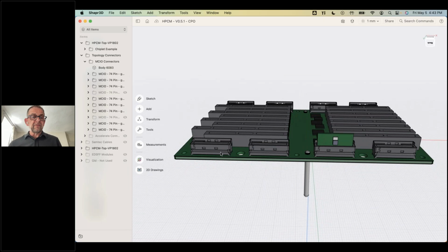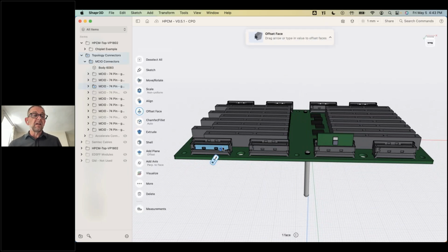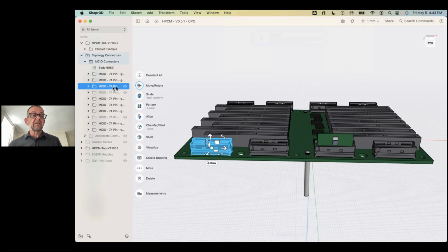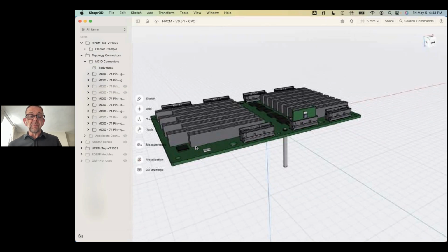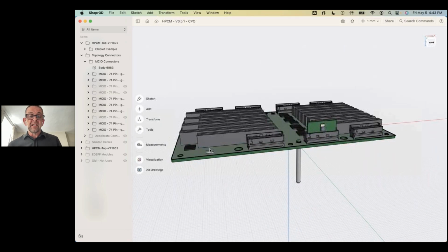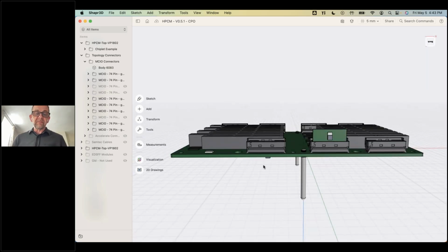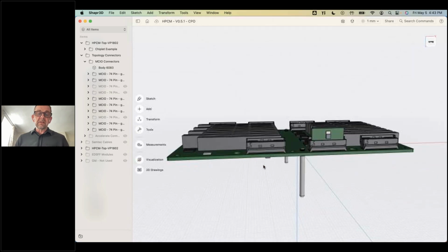So that's that. If I just peel these off a moment, let me just hide that one. Here you can see I've just put the optical chip on the back side, and so there would be an alignment issue, right? So how do you get the alignment? When you're stuffing these optical modules, you might need to go through some sort of active optical alignment, so that when you plug in the connector, you get a proper optical alignment. That would be a manufacturing process you need to go through.